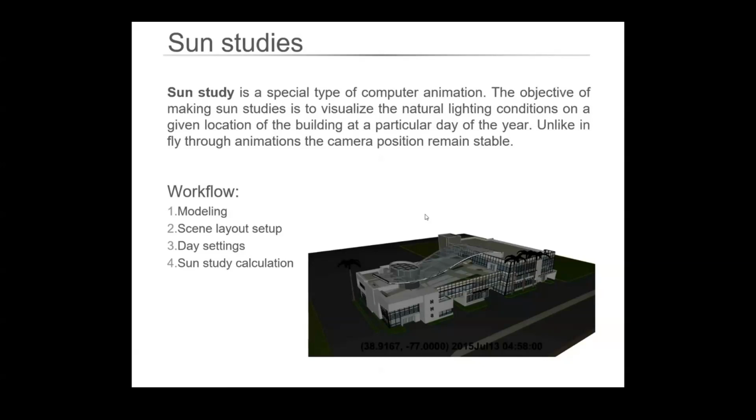And the sun studies is basically, again, taking your model and going into the sun studies section of ArchiCAD, which is in the creative imaging area. Has anyone used that at all for anything? Then you can go in and set building location, day, time, whatever you want, and it will create an accurate sun study based on those parameters. You can create photos of specific times of day.